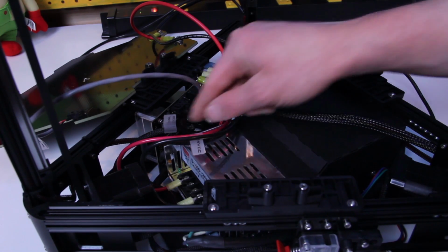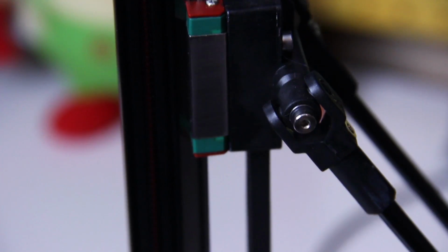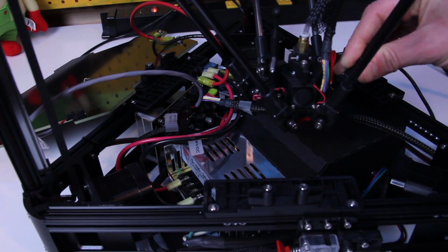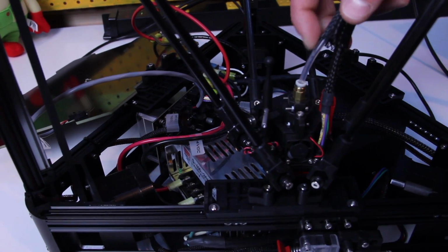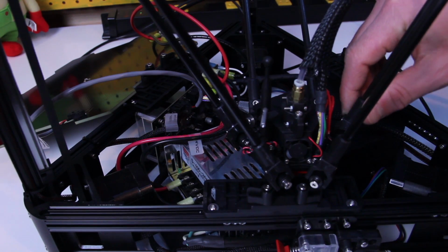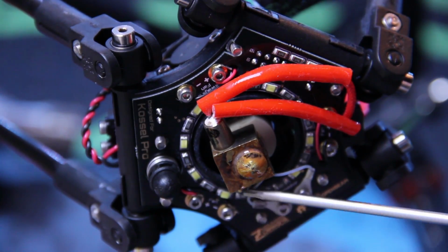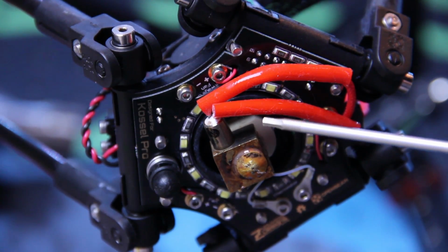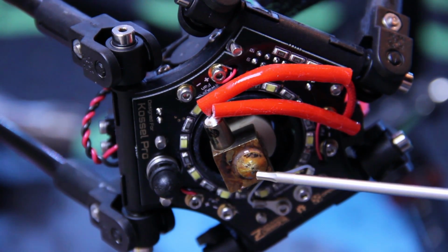Lots of wires and cables go to the different axes, and this is the main harness that travels up to the end effector, which is right here. This is the other end of it right here. The filament is fed through this tube into the hot end and is printed through the nozzle. This is a printed circuit board that has a bunch of LEDs on it. And in the middle here is the hot end, so that plastic comes through and is extruded out this nozzle, which is 0.35 millimeters in diameter, and it's laid onto the print surface.